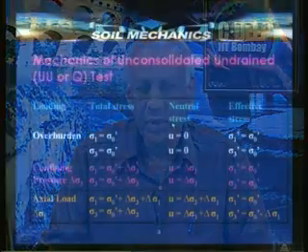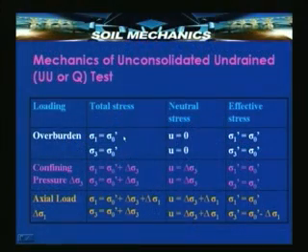In fact, the testing procedure is such that initially we subject the soil to a pressure equal to the overburden pressure and then we continue the test. So, overburden pressure is, let us say, sigma 0 dash, then that is the effective pressure sigma 1 and sigma 3, no neutral pressure initially, and the effective stress is sigma 0 dash as shown here.